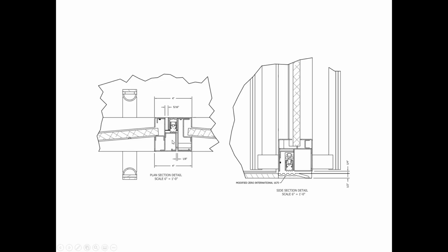Here we have at the jamb, you pull the handle out and it swings like this. So it comes in and presses up against this, and that's adjustable so that we get a good seal there. And then on the bottom, this seal here drops down from the bottom of the door. When the door closes, this gets depressed and that drops it down, so it seals.